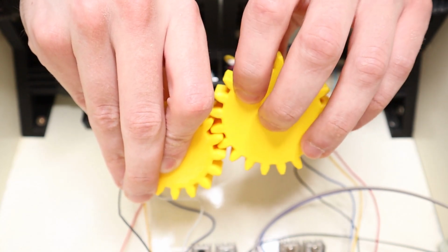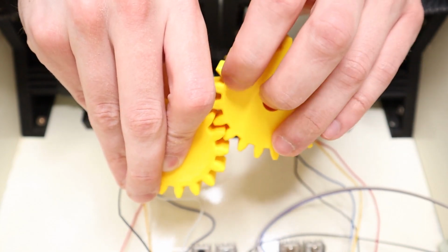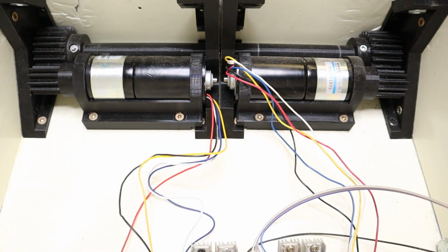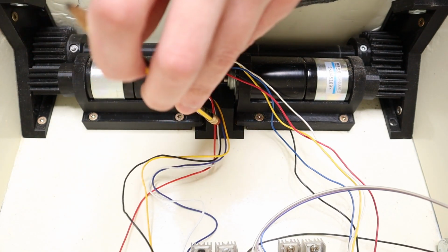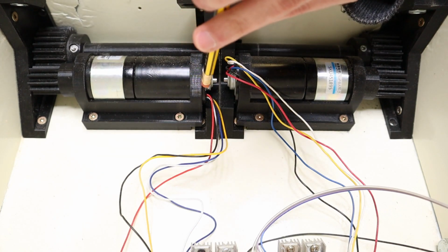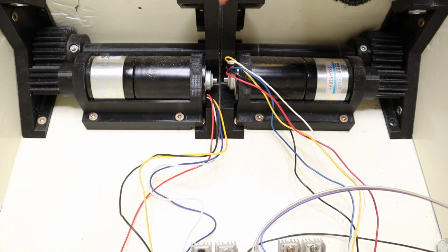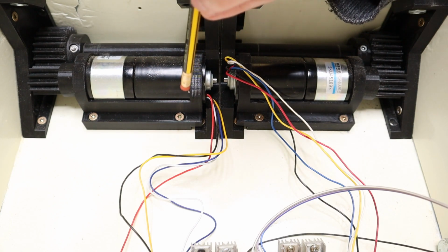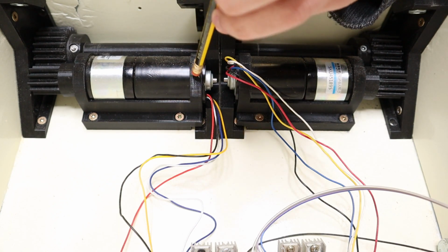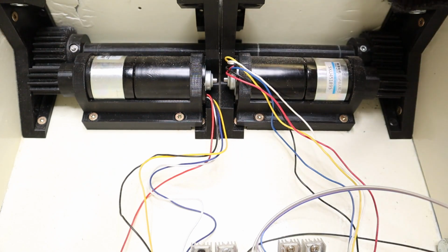So it's all bad, and the way to prevent this is by ensuring that the bearing housings over here and the motor housings are both sufficiently rigid and that they are also rigidly mounted in such a way that they cannot come apart. And so for this reason, it is also very important that you choose a stiff material to make these housings out of.